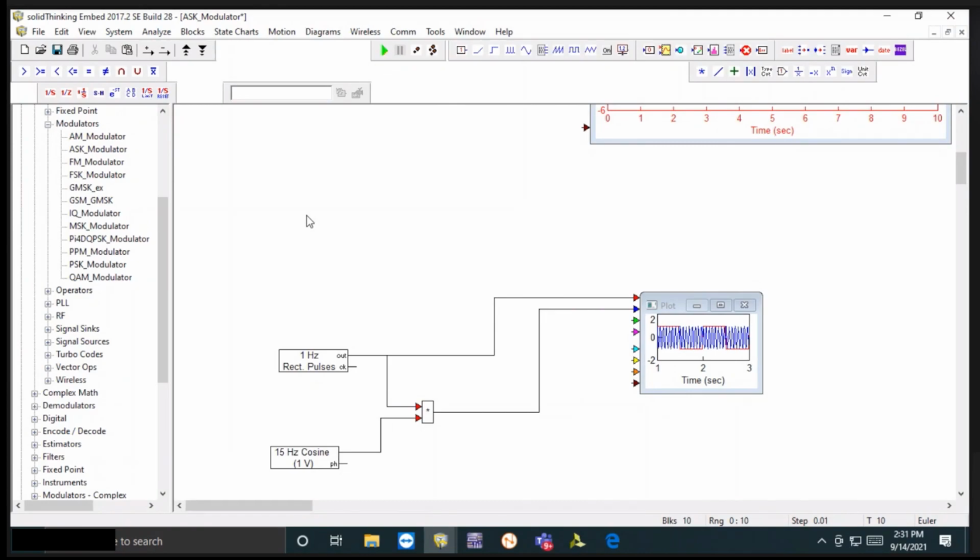How will it vary the carrier signal? We'll add a delta value to this carrier frequency omega. So we'll have an equation like cos of omega, that is 2 pi f, plus delta into d(t). Now delta is the amount of change you want to apply, and d(t) is the message signal.